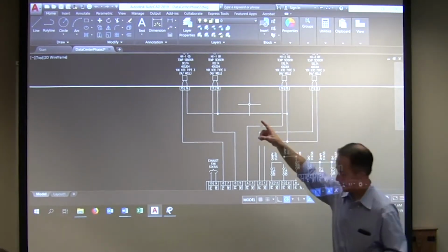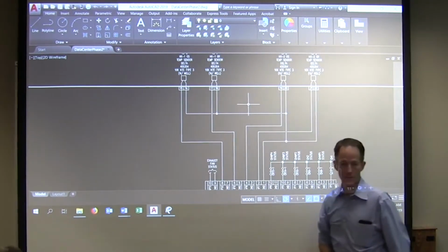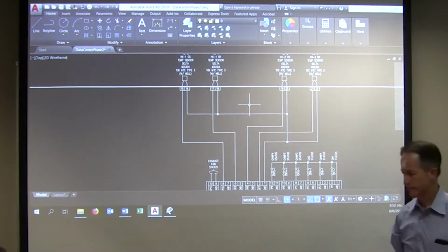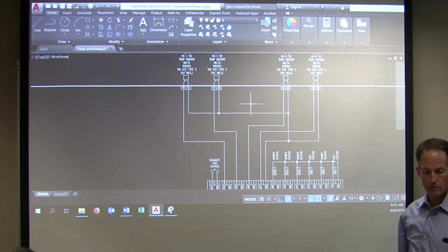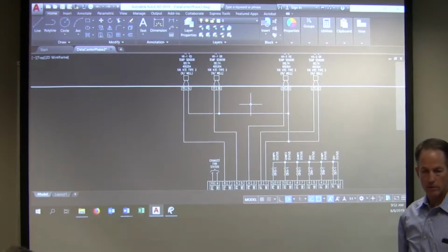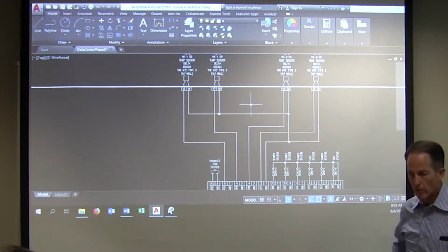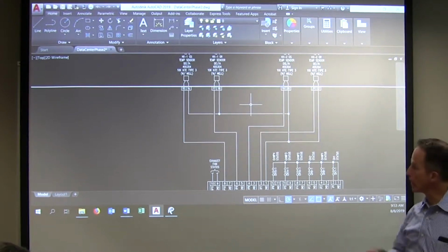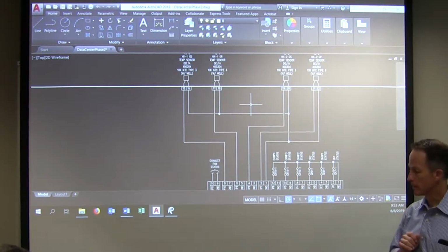And this tells me here, I'm a 10K NTC type 3, right? So at 45, it's 21.24. So are you on the type 3 or the type 2? Make sure you're on the right one. Type 3. Okay, Type 3.